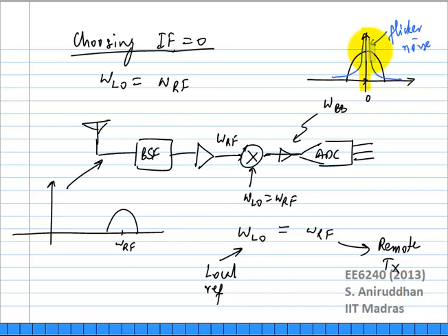Of course, a simpler, more modern solution, if you have a broad enough signal, is to choose not to transmit anything at DC, because this will be up to a few kilohertz, right? Your signal may be 5 megahertz or 10 megahertz wide. Most modern systems use OFDM modulation, where you have a whole bunch of subcarriers, maybe hundreds of subcarriers even. All you do is choose, around DC you don't transmit anything, or you don't care about what you transmit, and you don't have to worry about it. Your data rate will come down by very little, because you have hundreds of carriers. That is another way to do it. There are many ways to do this.